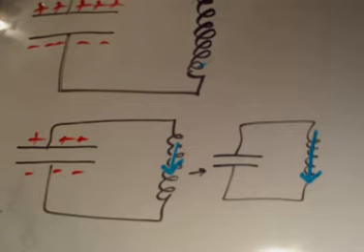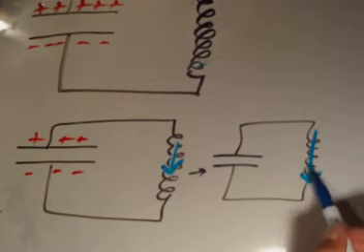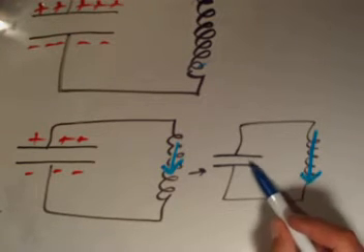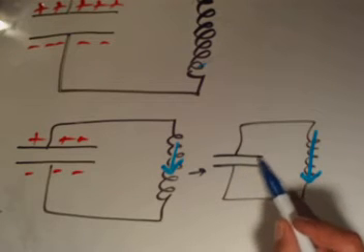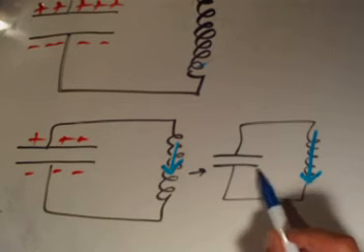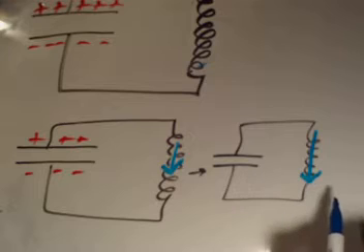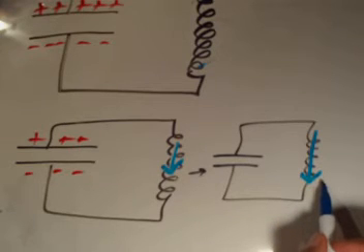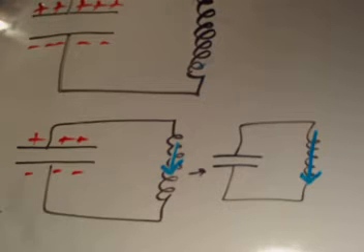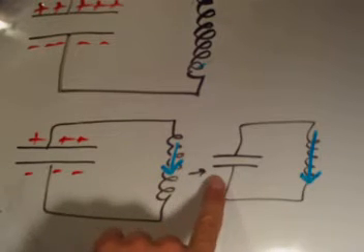Well, the consequences for the inductor get kind of interesting, because the inductor sits here with this huge magnetic field and sort of looks back at the capacitor and goes, hey, are you still going to give me any of your energy? And the capacitor is going to go, no, I don't have any more left. My plates are empty. So it's almost like you're pulling the rug out from under the poor inductor. You've given it this big magnetic field, but you haven't given it any way of sustaining that magnetic field because the capacitor is now empty.